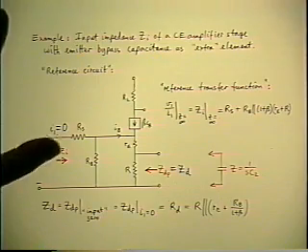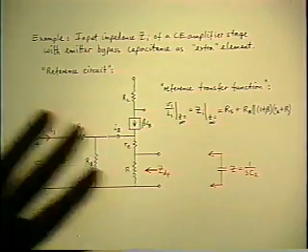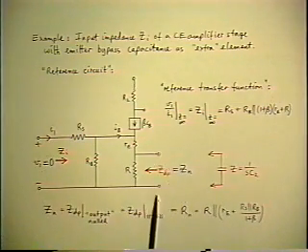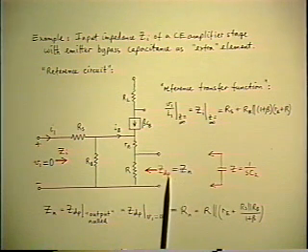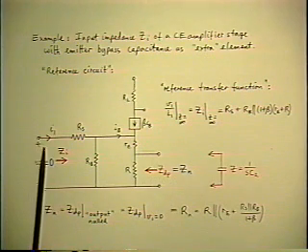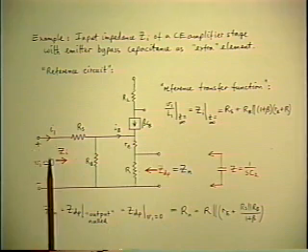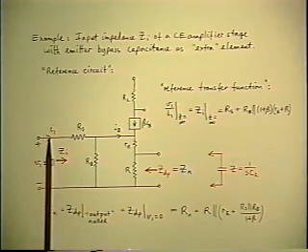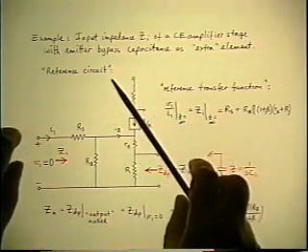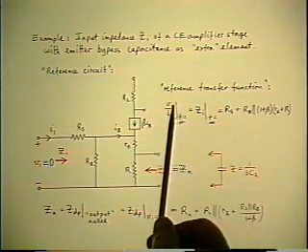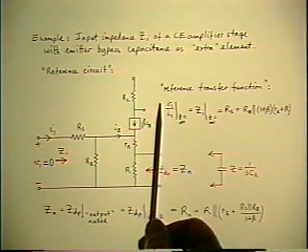So that's the first driving point impedance. The second one, again, I'm not bothering to redraw the picture. We again imagine the second source applied across these two terminals, and we're going to calculate Zn now under null double injection conditions, which means the original input is restored. The original input is I1. So there's an I1 that we imagine being put into the input terminal again. And we're going to adjust those two inputs in order to null the output. What is the output? The output is the quantity in the numerator of the transfer function of interest, which is V1.